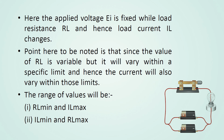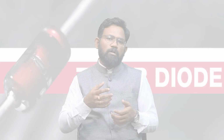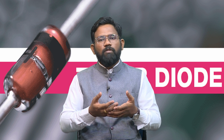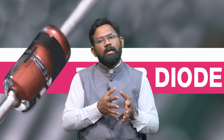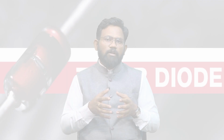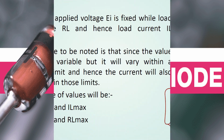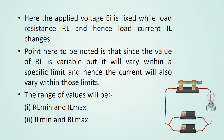So, here the applied voltage Ei is fixed while load resistance RL, and hence load current IL, changes. As the load resistance is variable, the load current will also change. So IL will not remain constant; it will depend upon the value of RL. The point to be noted is that since the value of RL is variable, it will vary within a specific limit, and hence the current will also vary within those limits.